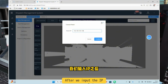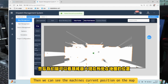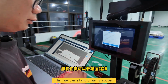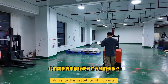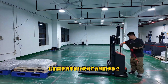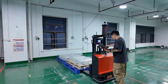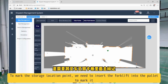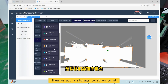After we input the IP, we click enter. Then we can see the machine's current position on the map. Then we can start drawing routes. We need to move the vehicle, drive to the pallet point it wants. To mark the storage location point, we need to insert the forklift into the pallet to mark it. Then we click Add Point. Then we add a storage location point.